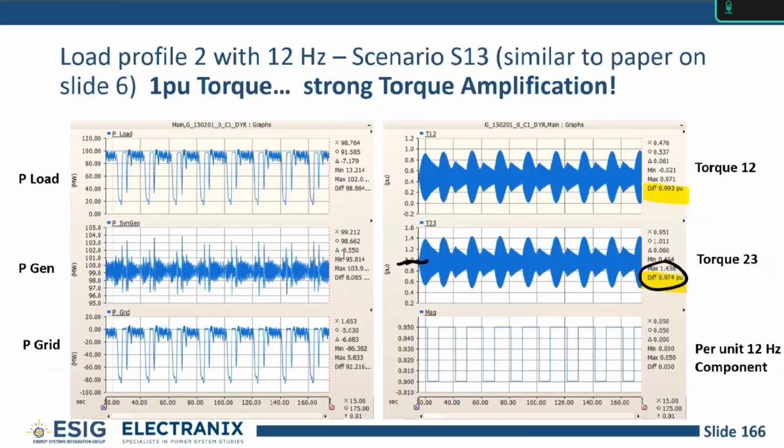Yeah, that's a good point. If you have a type 3 wind turbine, we didn't get into that in this course, but you have a mix of electrical interface to the grid and mechanical interface to the rotor of the, let's call it induction machine, asynchronous machine, whatever. And we'll see some of those currents showing up there. So you can get maybe some gearbox wear or something. I think a little bit of extra temperature maybe, and type 1 and 2 wind are directly connected without the power electronics interface, but those are going away anyway. So yeah, it's a good question.